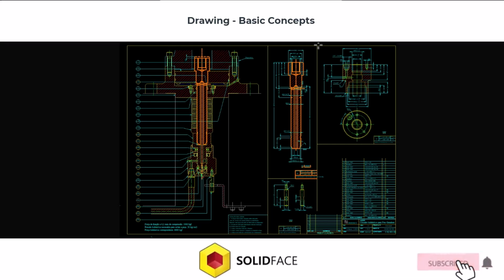This video explores creating and manipulating entities within a 2D environment. It highlights the distinction between geometric entities, lines, arcs, circles, and dimensions and texts. Emphasizes auto-associativity, where changes to geometric entities automatically update associated dimensions. Introduces the concept of groups and how to manage group visibility, activate groups for editing, and apply operations to passive groups. Parameterization is presented as a powerful tool, enabling the use of variables and expressions to define command parameters, allowing dynamic adjustments to drawings.